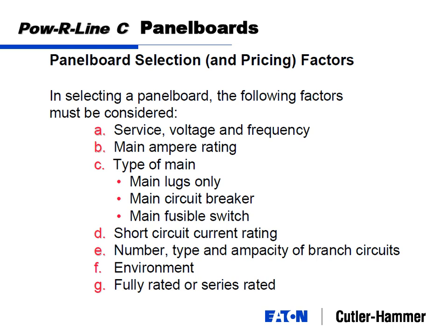So would they just go to the disconnect out there, the meter socket, shut it down from there if they needed to? You had that switch on the meter socket too. It's not rated as a disconnect. Oh, it has to be rated as a disconnect. Correct. Now, I don't think you can do service entrance equipment outdoors, but you probably have to have that discussion ahead of time.